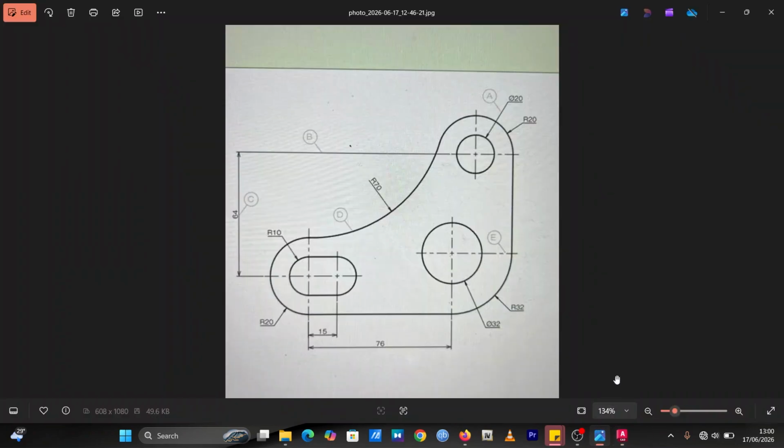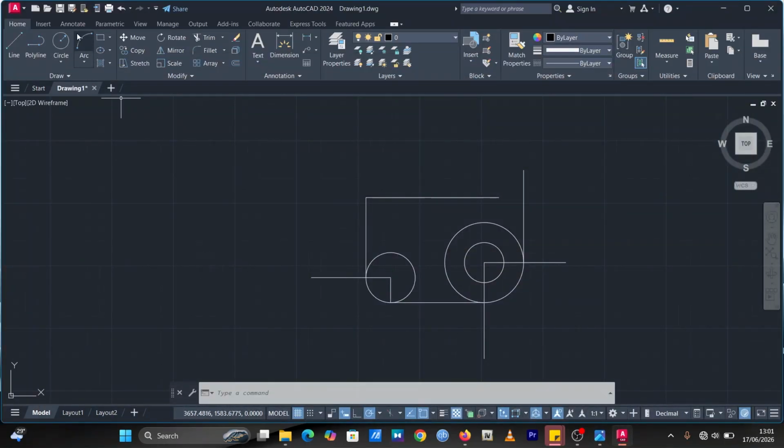Now we are going to make a drawing of this circle with the radius of 20. The outer circle has a radius of 20, and the inner one has a diameter of 20, which its radius is going to be 10. So let's do that. You pick your circle tool, you come to the tip here, because we already subtracted the 20. So you click, that will be our midpoint, and then you input your radius of 20, you press enter. So you see it's going to touch this line right here. You pick your circle tool again, you come to the center here, you click, and then you input your radius of 10. Now we are going to have something like this.